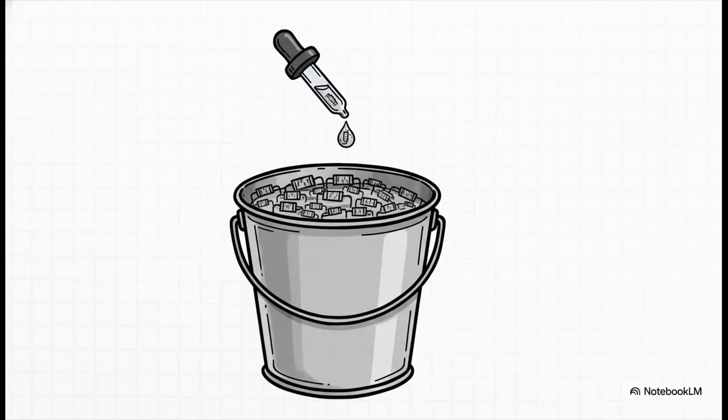So the key thing to take away here is that you don't always need the most complicated model. That tiny internal bulk resistance from our third model, it really only matters if the other resistances in your circuit are also super small. If they're not, that little bit of resistance is just a drop in the bucket. You can usually just ignore it.